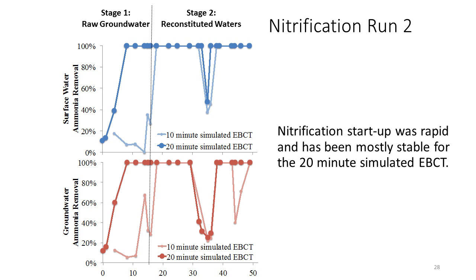So what we wanted to do was choose a lower value so that if you scale it up based on the particle size and the amount of biomass that would accumulate, it would be more representative. Obviously, it's not the same thing, but more representative of what a full-scale plant would look like. So you're scaling based on the amount of biomass. It's like an RSSCT. Okay.